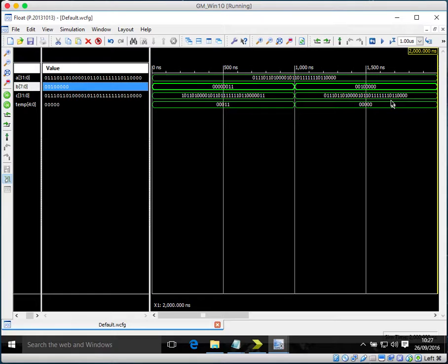And basically why this happens is that after shifting the output 31 times, the 32nd shift is nothing but a shift by 0. And that is why I am just choosing the first 5 bits and truncating the rest. That makes sense, as those are the 5 bits that determine how many bits I need to shift. And the same logic I've implemented for the right shifter as well. So this was the functional simulation.